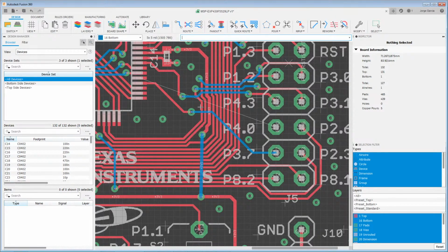You're going to notice there's a little bit of a lag, but you're going to notice a little error window pop up. Basically, as long as Fusion runs for more than 5 minutes, if it's not seeing anything done, it'll pop this up. Just hit OK if ever you see this and you're working. It's just that Fusion doesn't expect a command to be running all the time, like the select command can. So just OK it. That's something we'll deal with in the future.